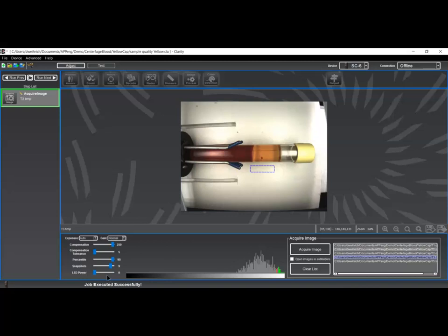These controls down here are direct hardware controls that control the acquisition process in the camera. There's some iterative work that has to be gone through to get these settings correct for the best uniformity of picture-to-picture and the best utilization of the illumination. It should be noted that the most critical part of machine vision operation is the lighting and illumination around the object.